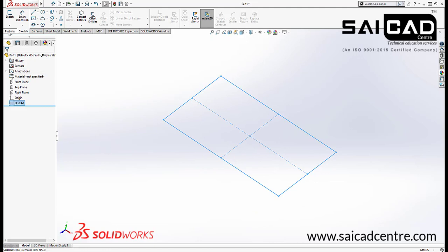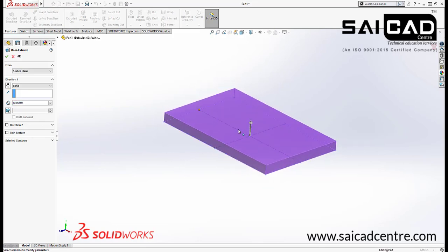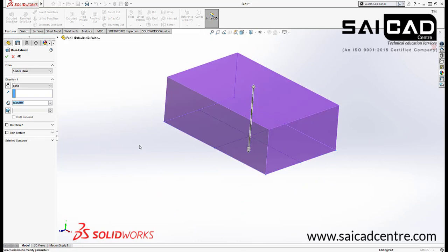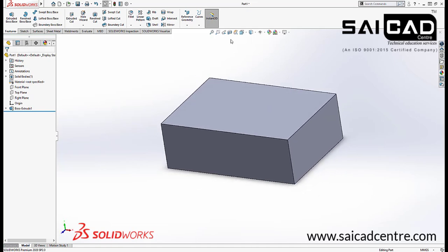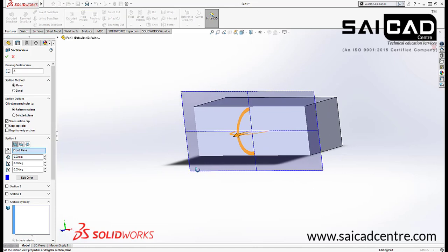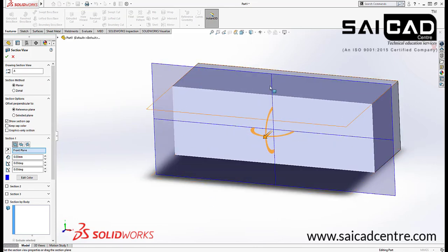Now if you go to the Features tab and use the Extruded Boss/Base, this command is for solid modeling. You can just drag it from here, and just click OK, and you will see we got a solid body right here. If you go to the section view and choose any plane or face, you will see the object is solid from inside also.